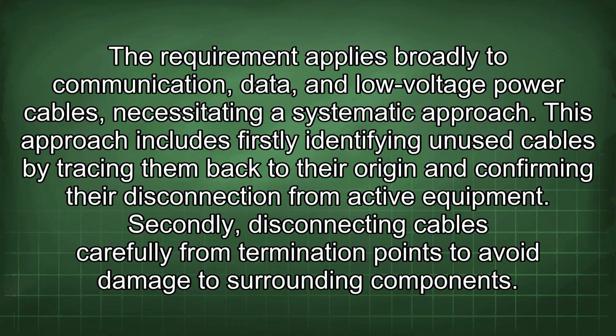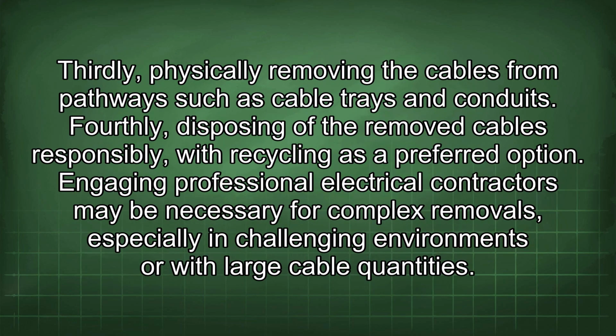Secondly, disconnecting cables carefully from termination points to avoid damage to surrounding components. Thirdly, physically removing the cables from pathways such as cable trays and conduits. Fourthly, disposing of the removed cables responsibly, with recycling as a preferred option. Engaging professional electrical contractors may be necessary for complex removals, especially in challenging environments or with large cable quantities.